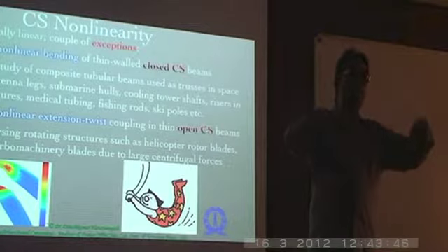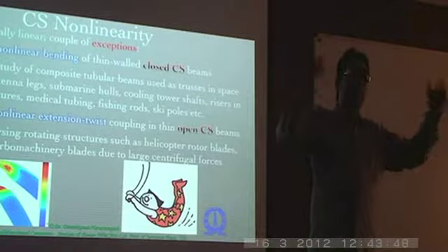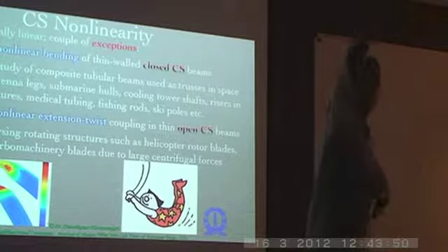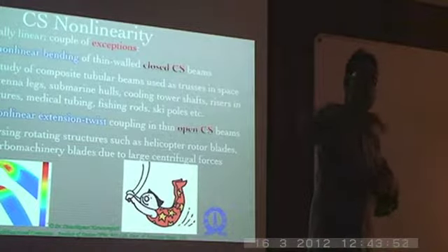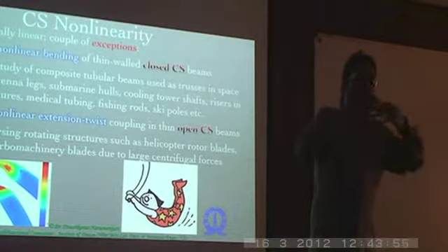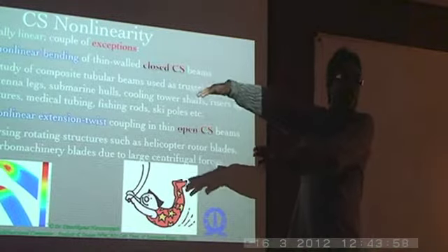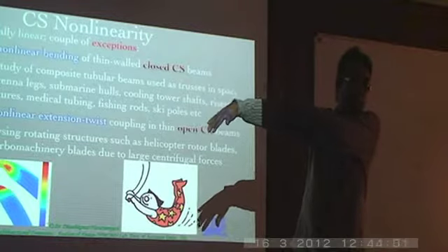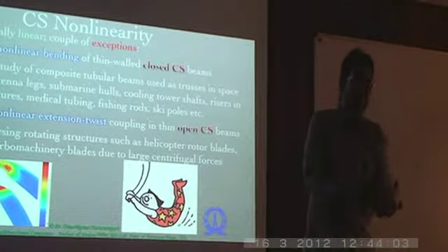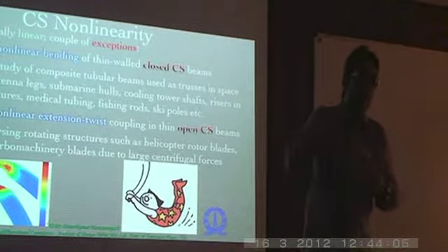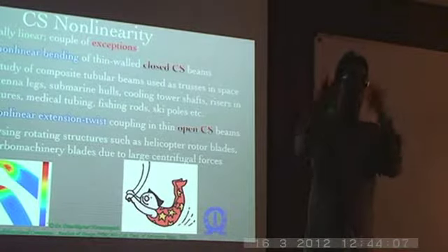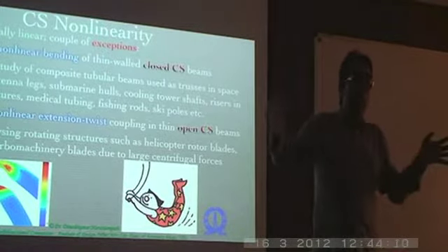So that concentrated load, whatever you are applying through the wings, gets dissipated through the bulkhead into the length of the fuselage. So that way there is an effective transfer of loads. Again, in the wing where the engine is attached, you will find transverse stiffeners, the ribs. So again, the weight of the engine as well as the thrust load which is coming because of that will get diffused into the structure.